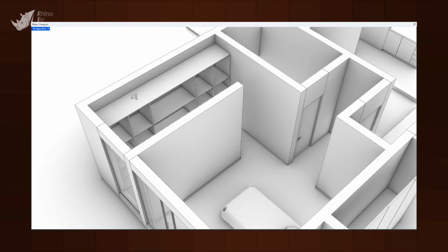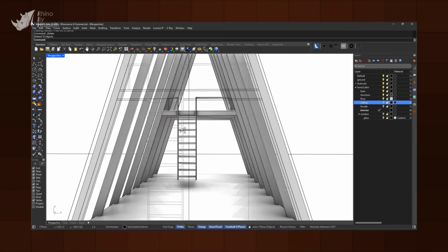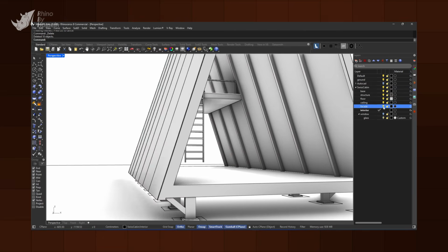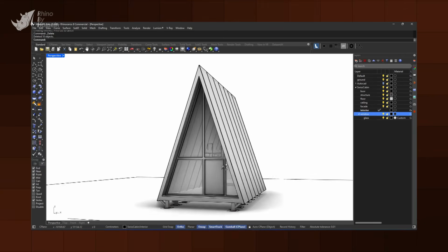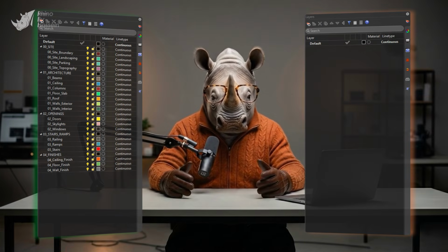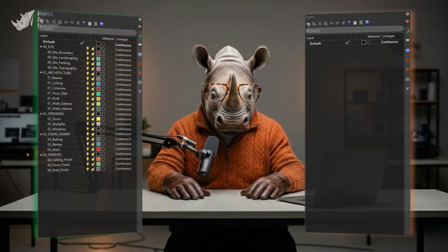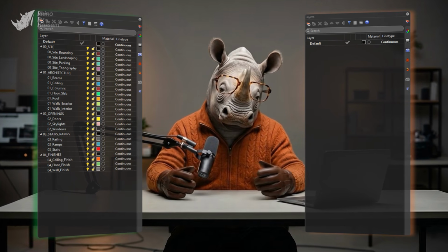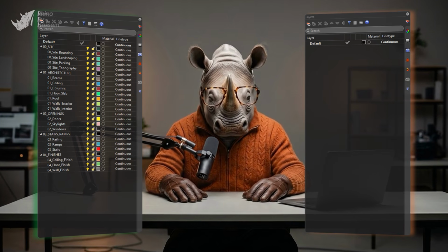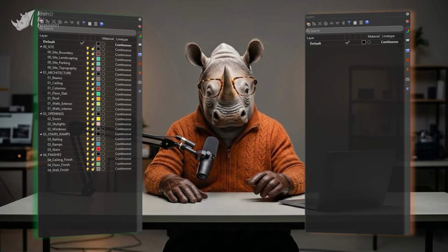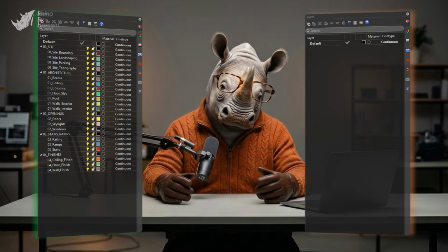You can't isolate just one part of the model easily, you can't apply changes to a specific section, and every small selection forces you to deal with the entire scene. Instead of a controlled model, you end up with a messy space where finding and managing elements becomes time-consuming and exhausting. The solution isn't complicated. From the very beginning, you need a simple and logical layer structure. For example, separating things like reference curves, surfaces, and details. It might feel unnecessary at first, but it's exactly this kind of basic structure that keeps your project under control and makes everything significantly easier as it grows.